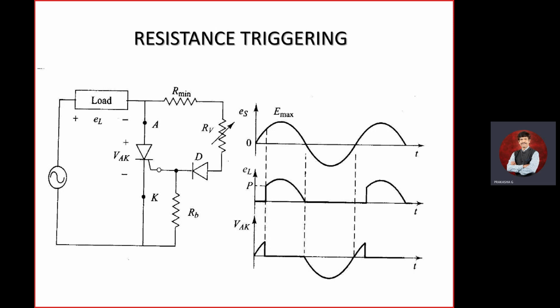As soon as I want to measure the output voltage, because you have done rectifiers, you are supposed to measure the output voltage, the current and the voltage. Sometimes what happens, I am not getting the output voltage properly. So don't sit idle. You should not say, sir, I am not getting the output. It may be a component problem, or the component connection is not correct. All those issues will be there.